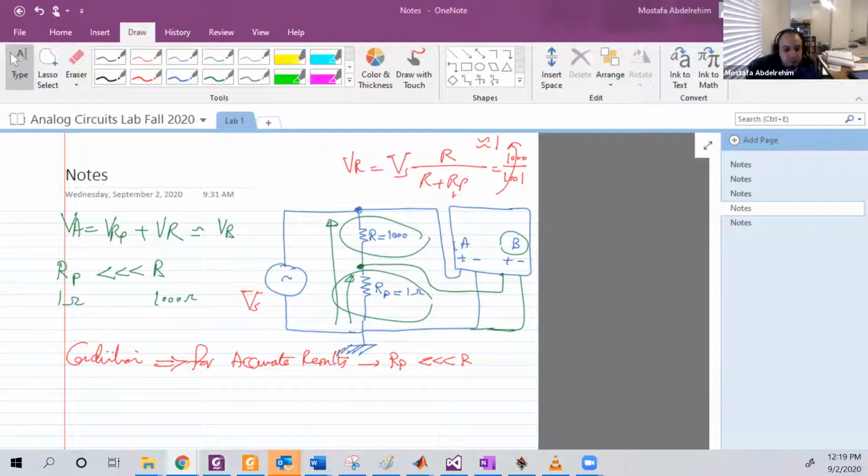Okay. Now you will do that. You will take the screenshot. Then you will change the resistor to 2 values. One is 10 kilo ohms, much larger than 1 ohm. And then you change the resistor under interest to 0.1 ohm. Let me see what you're gonna have.